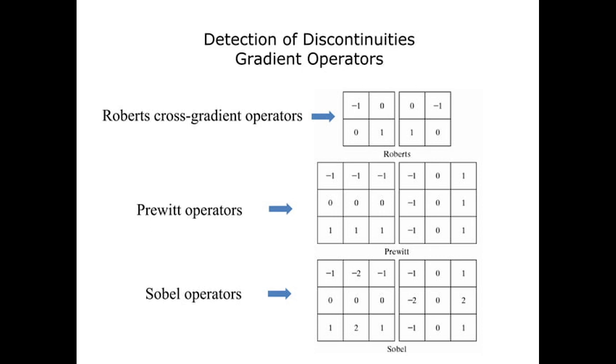So from ordinary masks, so far we have discussed in filters also, averaging filters, weighted average, whatever, it is not so. But in the difference operator, difference mask, you can find this changes. So this Roberts is also an edge detector. These three masks are very famous masks for finding out the edges. So this is cross gradient.